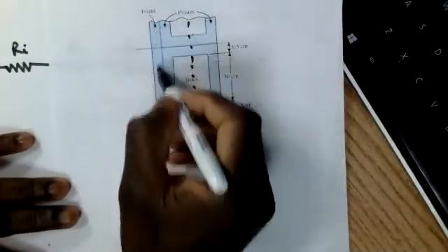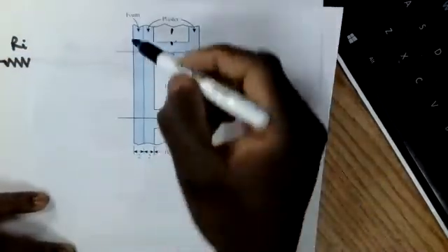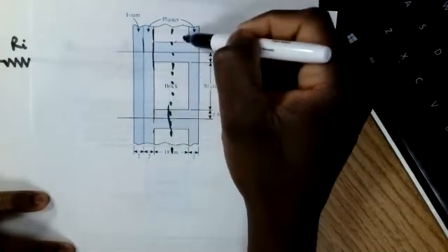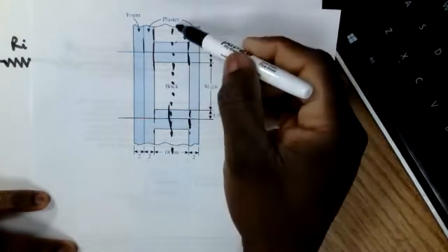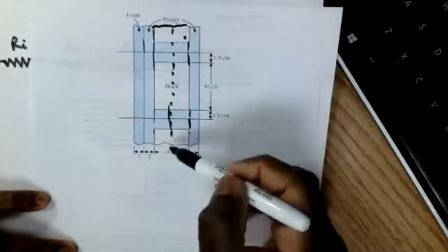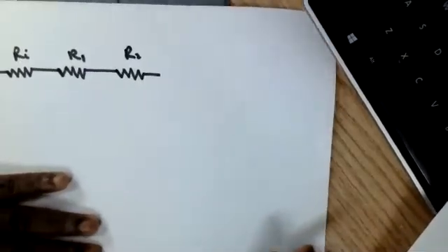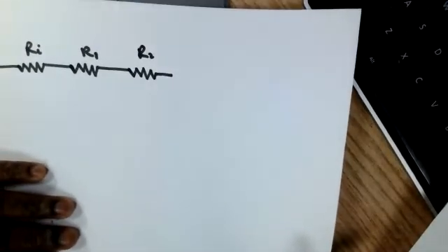Now, up until this point, we have these surface areas existing. It's a homogeneous material up to this point. But by the time we get to this region, it's no longer homogeneous. Okay, we have multiple materials. So there's a way of evaluating a region in the wall where you don't have one material. And I'm hoping that you've done this in class. Okay, it's similar to the parallel arrangement of resistors in an electric circuit.